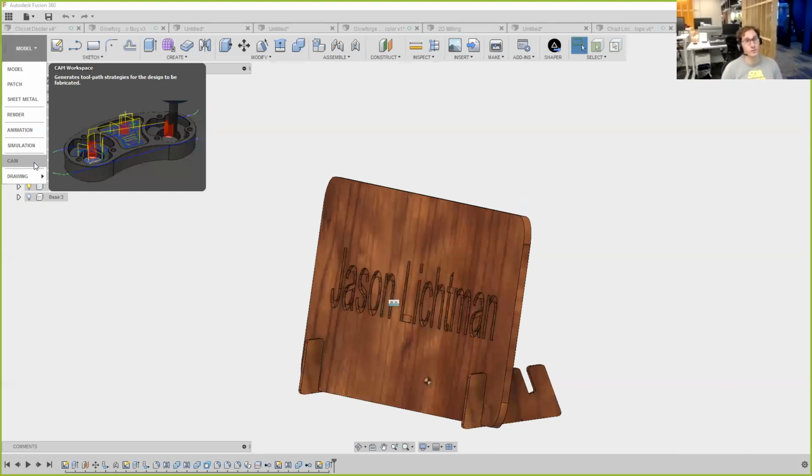And what I will tell you that you should do then is make sure to either sketch everything as a single sketch or create them as separate sketches and then make one final sketch at the end that combines everything. Take that sketch, save it as a DXF, bring it into Illustrator, separate it out into different layers of different colors if you'd like to have one thing be cut, one thing be scored, and one other thing to be engraved. Copy your layers if you need an individual thing to be scored and engraved. Copy that, make one scored and one engraved, and so on. And then send that to the Glowforge.